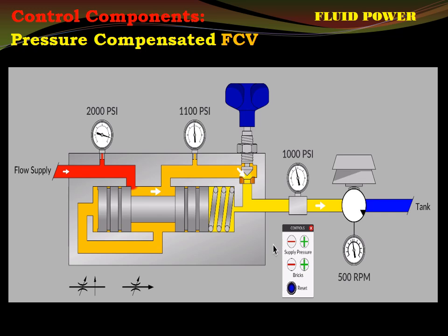Okay, see everybody here, this is the compensator spool, as I said, meaning it is movable automatically. You don't have to control it. It is driven by a spring. The spring is compressed, always forcing it towards left. Always forcing it towards left. Okay.